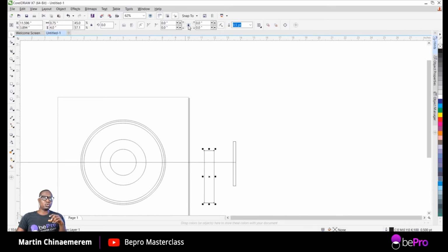In other words, for us to do that, we have to unlock, because here it's locked already. If it is locked, see what happens. Once you select a particular radius, let's say 25, automatically it applies to every corner: the right, the left, the left down and the right down. So for us not to have this mistake, because we are only applying the radius on one, we have to unlock by clicking on the key icon there. Once we do that, we can apply 0.25 to the left down corner, and hit our enter key. Once we do that, we have what we wanted.